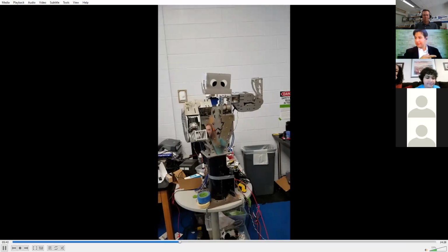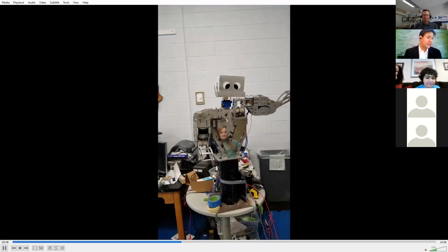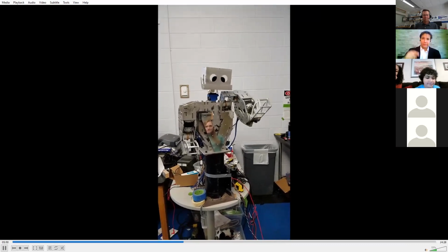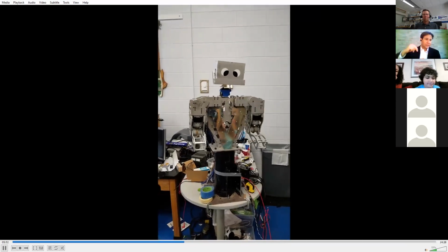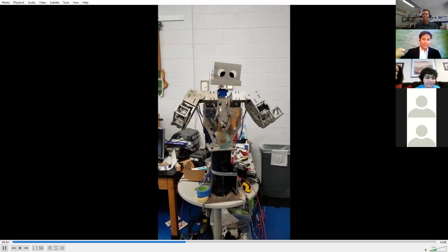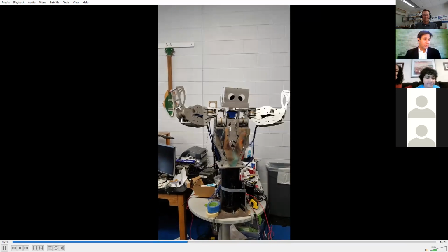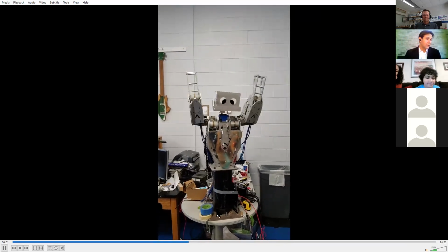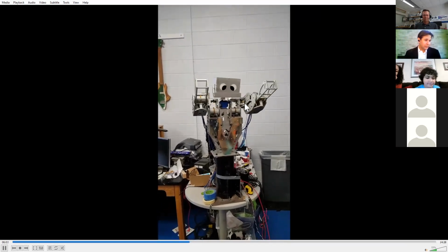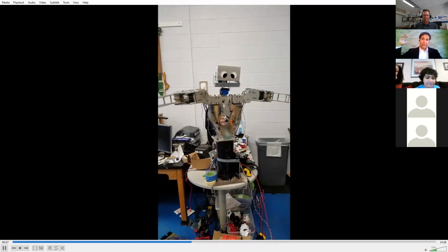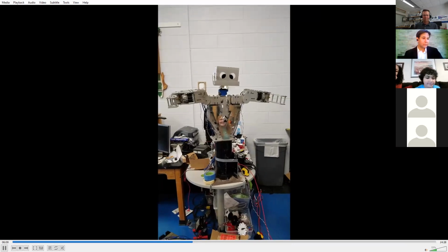So Kevin, check this out. This is a robot that our students built. It's all made out of metal. So we have a water jet machine that can slice through up to 6 inches of steel because it's got 60,000 PSI of pressure with abrasive garnet dust mixed in. So it's kind of like liquid sandpaper. So basically it just pressure washes through, in this case, 1/4 inch aluminum to make all these parts. Another interesting thing about this robot is that we're deliberately using worm gears so that once it freezes in a position and you lose power, it actually can hold that position. So basically one-way transmissions throughout the robot.